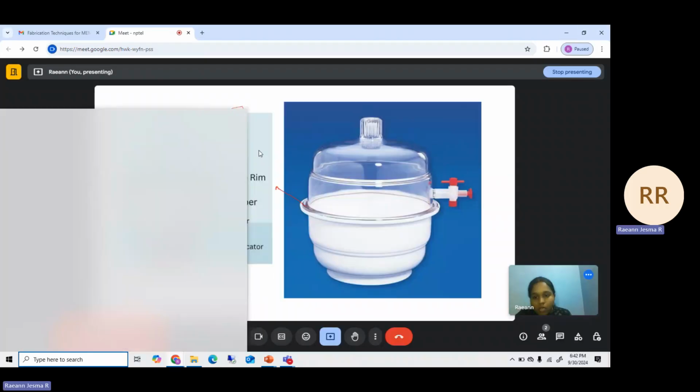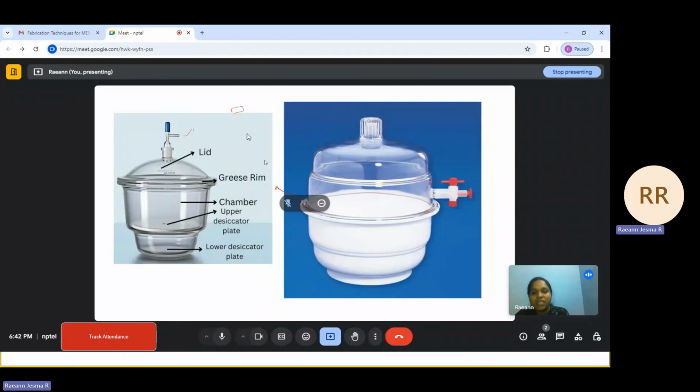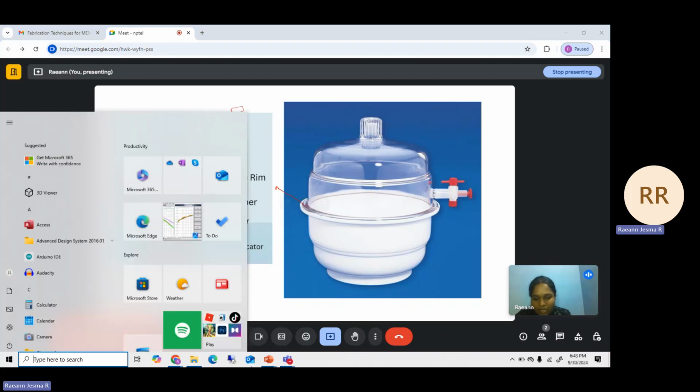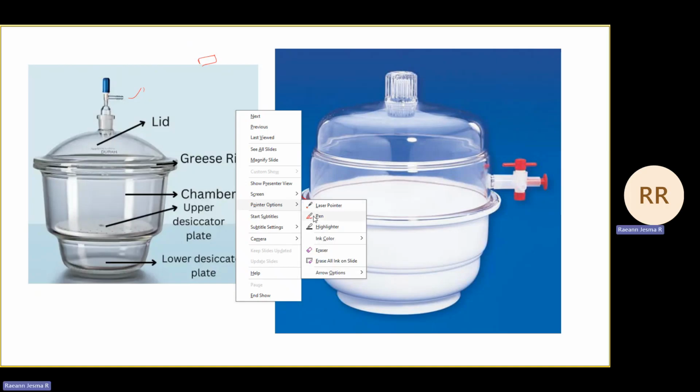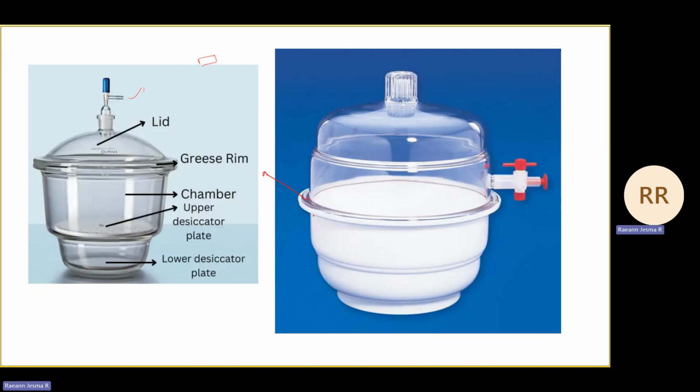So to avoid this, we'll have to keep our sensor in vacuum condition, and moisture also can affect your sample. For that reason, we'll keep our samples in a desiccator when we are taking them outside the clean room environment. This way, we can minimize any interaction of the fabricated sensor with any particles present outside. Is this clear? Now let us move on to the next question.